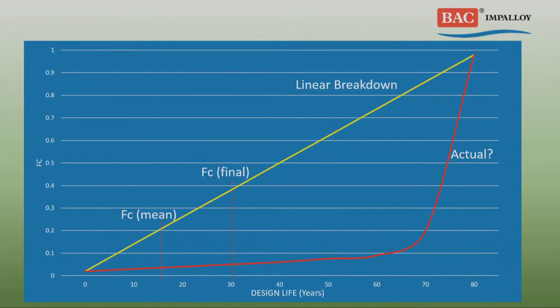In galvanic anode terms, it generally means for a coated structure, more anodes. For an impressed current system, we have to have bigger power units, bigger cabling, bigger anodes, all of which may not be necessary. For galvanic anodes, it's actually more serious because it has a real sustainability and environmental impact, because we calculate the amount of mass that we need to last the anode life by taking the mean current density.